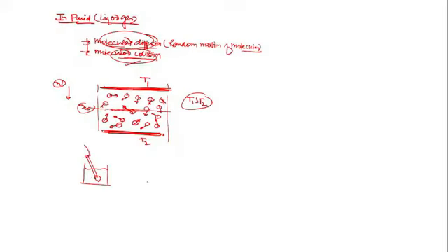How is it possible? Although only this end is exposed within the hot cup of coffee, this end also gets heated. It's just via conduction. When this end of the spoon is put in the high temperature, then, because it's conduction in solids, there are two reasons: the flow of free electrons and the lattice vibration. Due to vibration and the flow of electrons, the energy gets propagated, and this transfers energy from high temperature to low temperature, and immediately this side also gets heated. Is this clear? This is conduction.